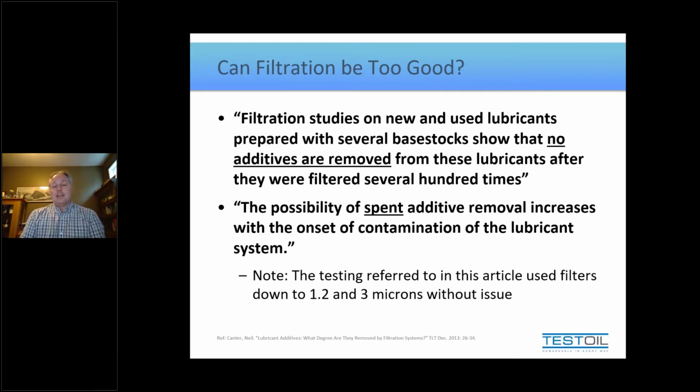But the point is, if you had, say, a dispersant additive in your oil and you had soot particles in it because it was an engine oil, and the dispersant bonds with the soot, if you filter out the soot, did you in fact filter out the dispersant too? Well, technically speaking, you did. But can you say definitively that a filter removes dispersant additive? No, you can't. And do you really care that it did? Because once it's bonded with the soot, it's already done its job. It's keeping the soot from agglomerating with other soot particles. So what do you care if the additive is there or not? It can't bond to another one.